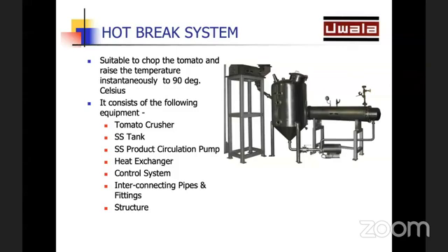And why is pectin important? Pectin essentially helps in binding the tomato pulp together. If you have seen ads of tomato products, we have generally seen that people try to show how viscous their product is, or how well the product is holding itself. That is essentially achieved with the help of pectin. And if we have to retain pectin in the tomato pulp, we have to ensure that we do hot breaking of tomatoes. So this process is essentially about retaining the pectin in the pulp.